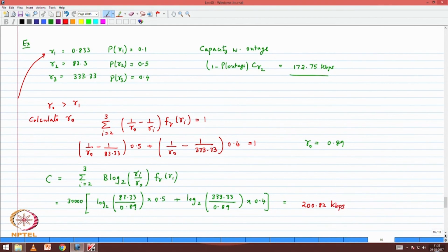Okay, that's a significant percentage. So actually, water filling can, in many channel conditions, do much better. But we still agree that water filling has a benefit. Therefore, this is something that we would definitely like to keep and exploit to the maximum. Okay, any questions? So water filling is all about finding the water level, allocating power such that the better SNR channels get more power under the constraint that there is a satisfying overall power constraint, and this enables us to get the maximum out of the channel in terms of the capacity.